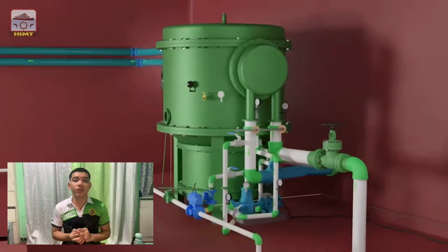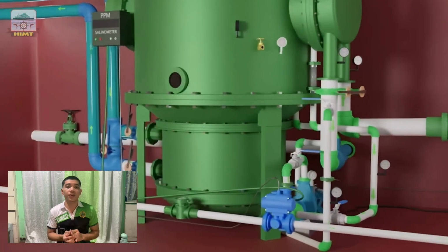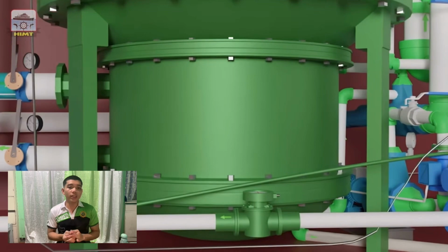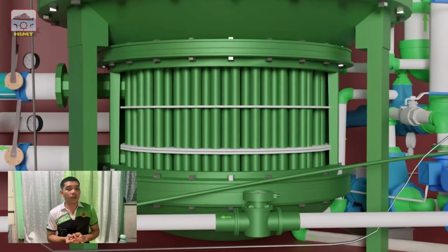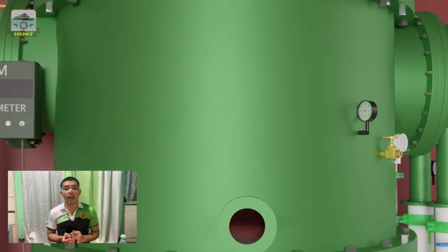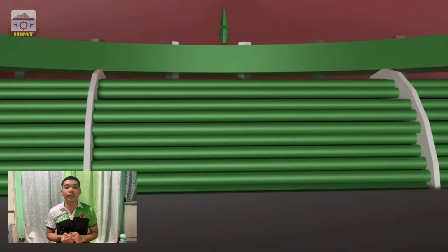At the heart of this unit, we find two vital heat exchangers. The bottom heat exchanger serves as the evaporator, which is responsible for the initial stage of the distillation process. At the top, we have the top heat exchanger or the condenser, a semi-cylindrical shell that covers only the bottom half of the tube stack.